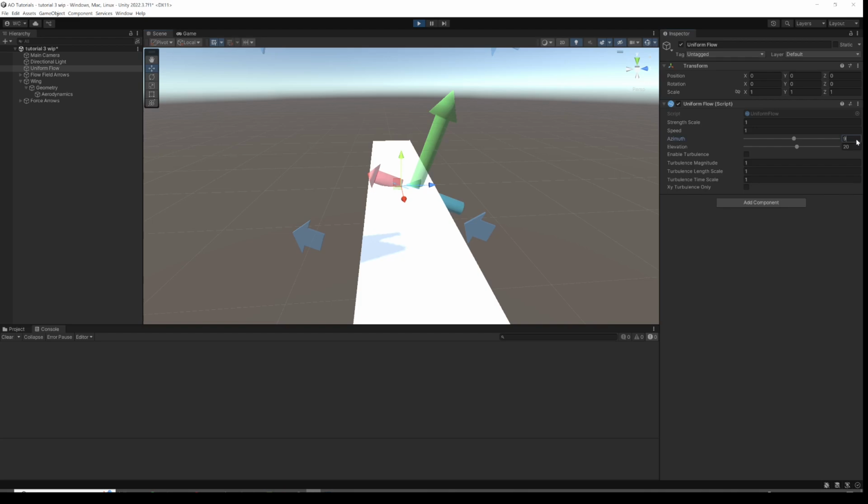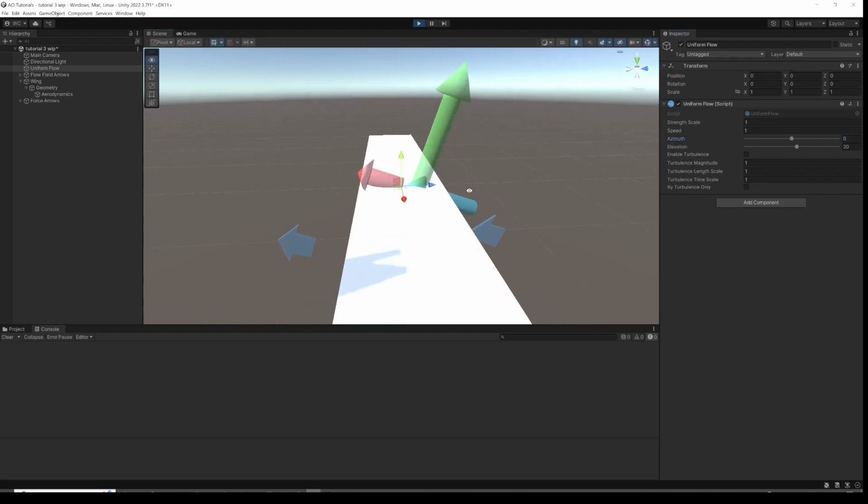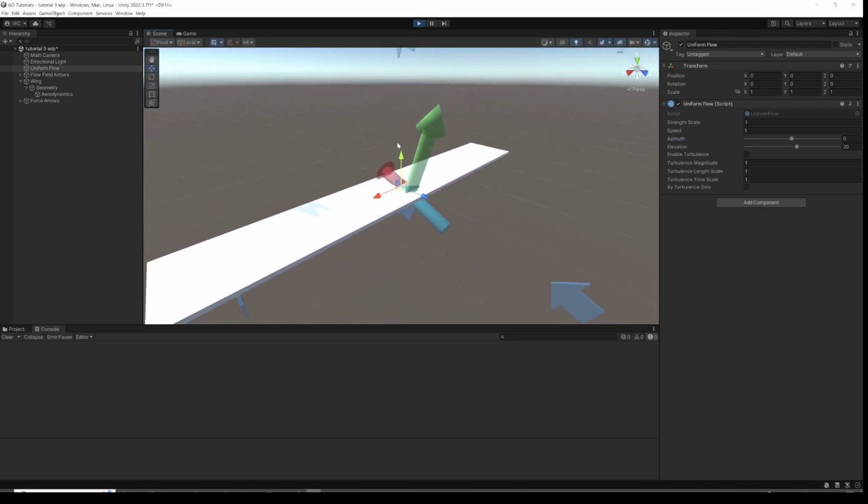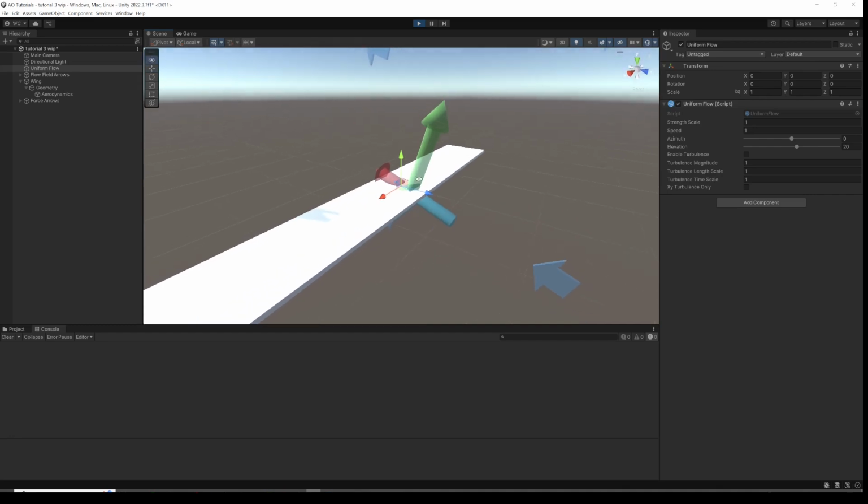The other thing we're interested in, in terms of our lift modelling, is that it really matters where the lift acts on this wing. Imagine this really was a ruler. If the lift is acting at the front of it, the front will tip up when it's flying. If the lift is acting at the back, it'll tip the other way. So for an aircraft, it makes a big difference where the lift acts.